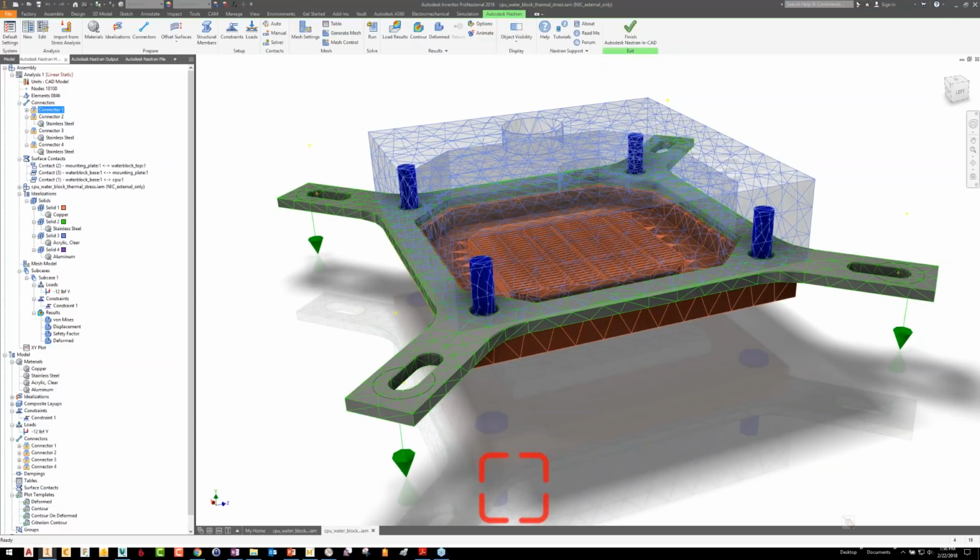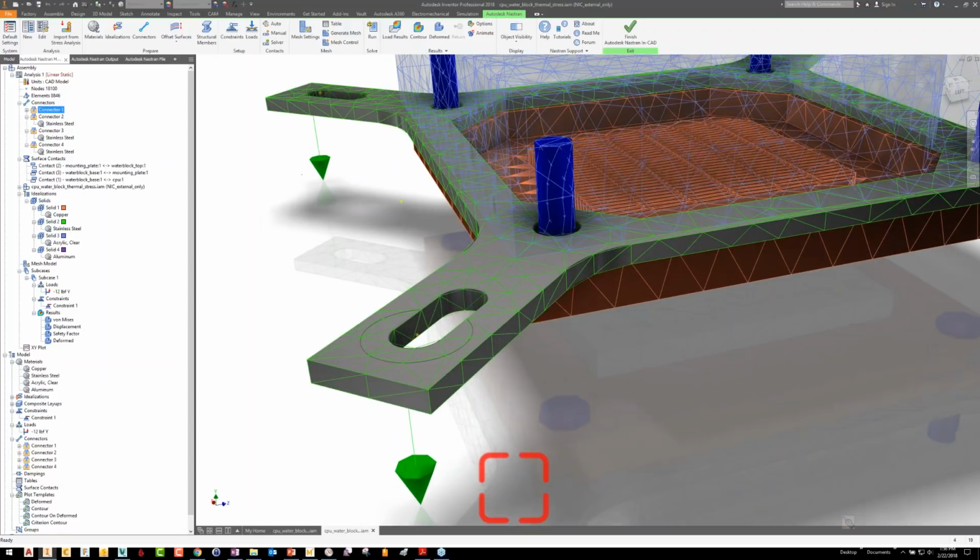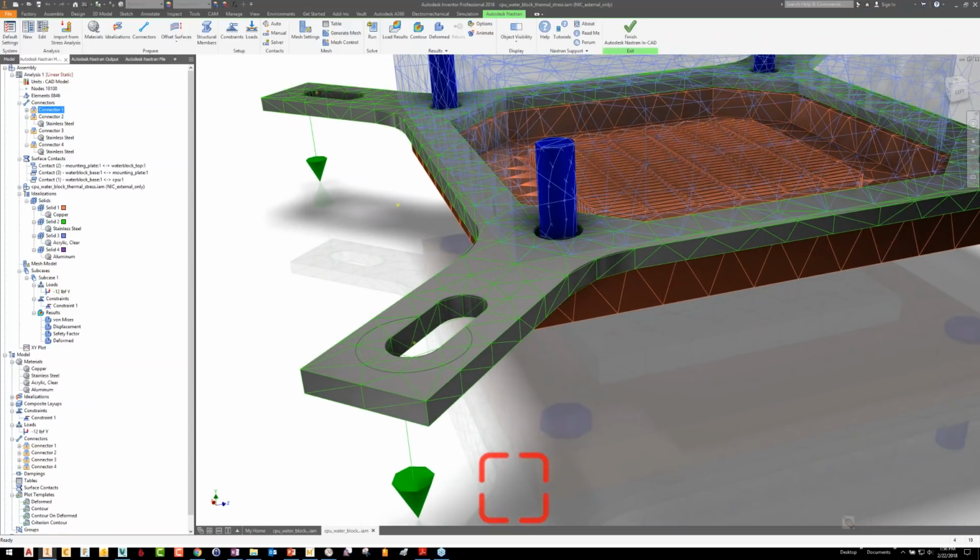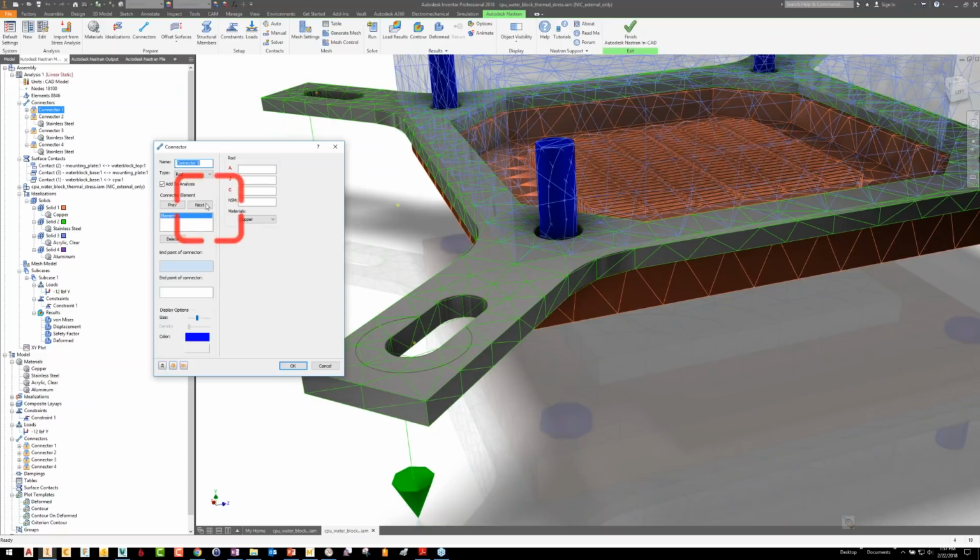So next, these areas here where I've just kind of put a force, I do want to put some stuff on here that won't necessarily change the result so much, but more to show you what it looks like to build these kinds of structures. But maybe if I was interested in how much my spring was going to displace under that 12-pound load, I'd want to include it here, but not a 3D model of the spring, right? So I would use instead another example of a connector, and it's the spring type. And let's just show you what that's going to look like.